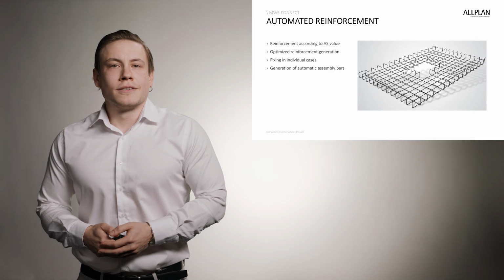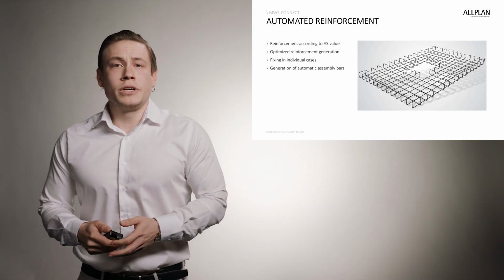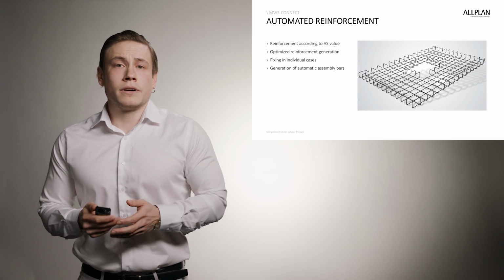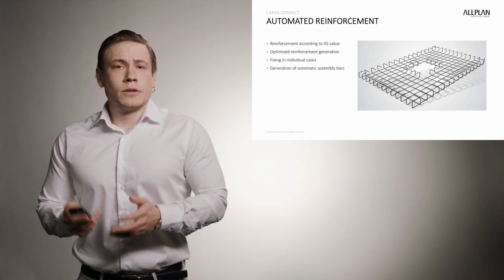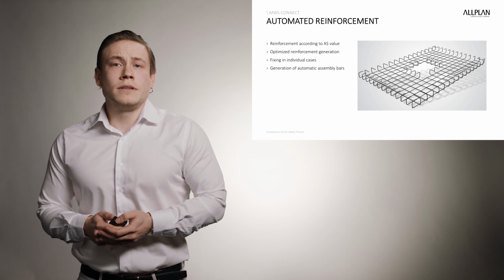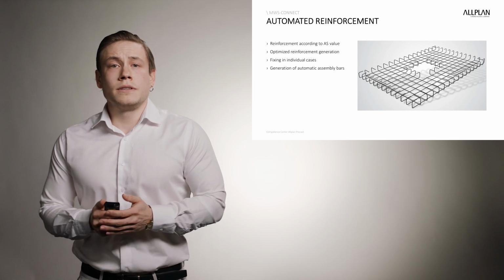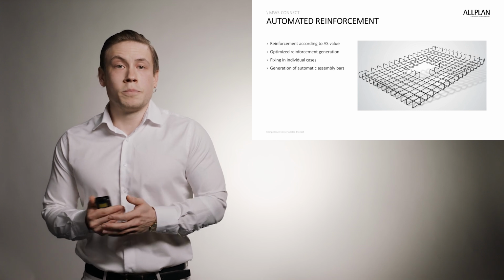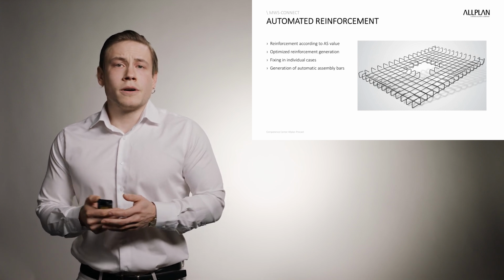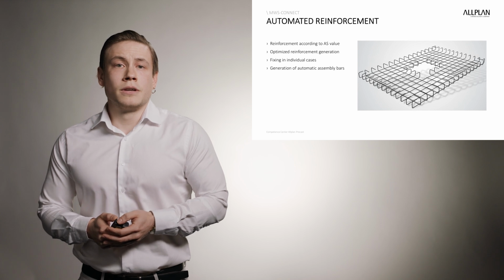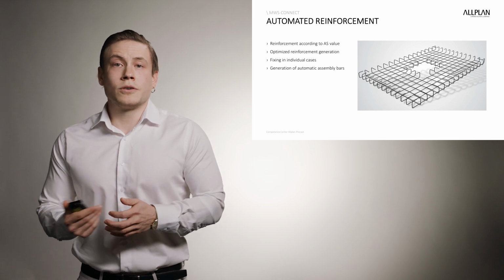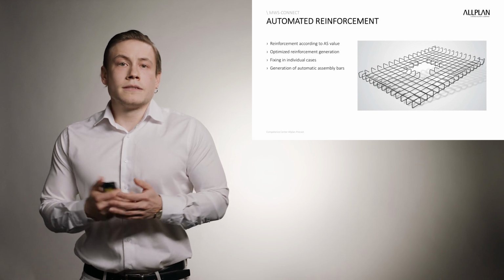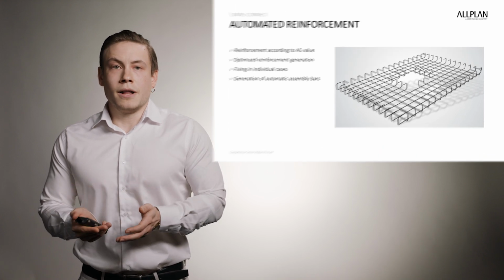The automation also takes into account any precast relevant parts, such as fixtures, and reacts accordingly. On the right picture, we can also see the automation also considering the cutting and bending of the bars beside the opening. If all bars would get the bending shape, we would have a problem later on in the workflow due to the overlapping. This is done completely automatically by ALLPLAN.